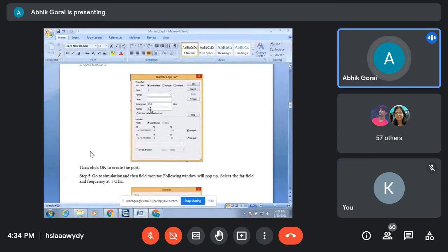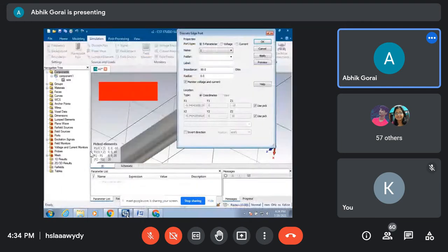Can you tell me why instead of 50 ohms, we are taking the impedance to be 73 ohms? What is the radiation resistance of a lambda by 2 dipole? You had done a derivation in your previous semester, and you ended up with a certain value.